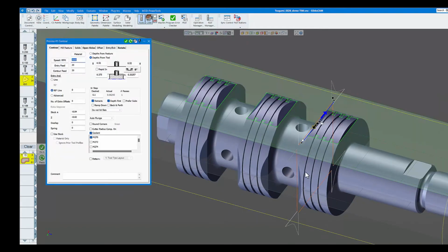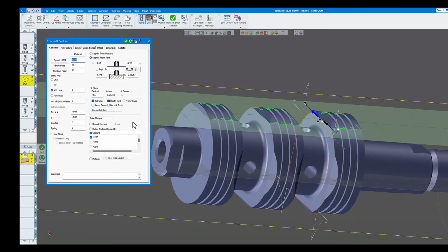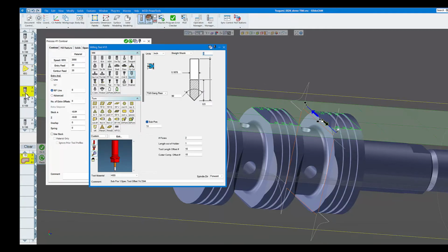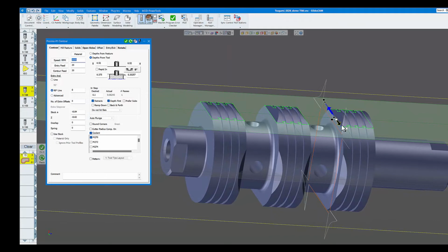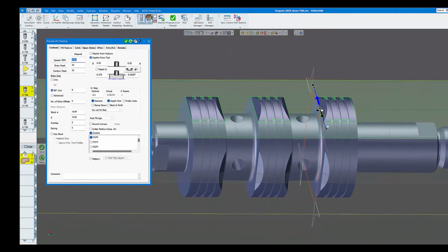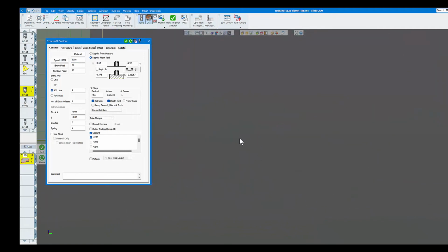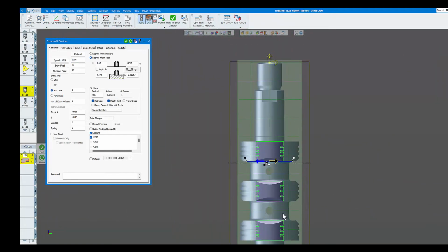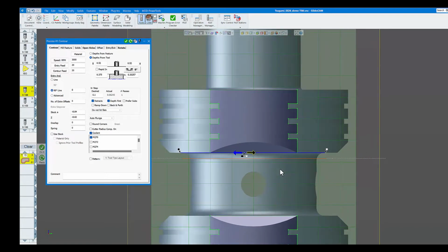So next, then we're going to take basically tool number 15. Let me find that there, which is this one here. It's kind of a combination spot drill, chamfer tool, and we're cutting the flats, not really flats, but kind of the angles on here at the 45 degree. And again, if I go to the home view, and this we're using the profiler again this time, or you can extract the geometry either way, but this is the surface that I want to cut.